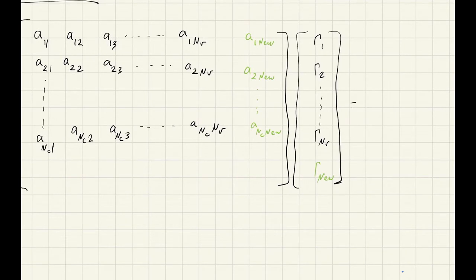Which is equal to, again, the right-hand side. We will go over forming the right-hand side in the next step, but for now, let's call it RHS1, RHS2, and go down to RHS and C. These right-hand sides are simply the velocities induced at each collocation point due to the free stream flow, as well as the shed wake right here.